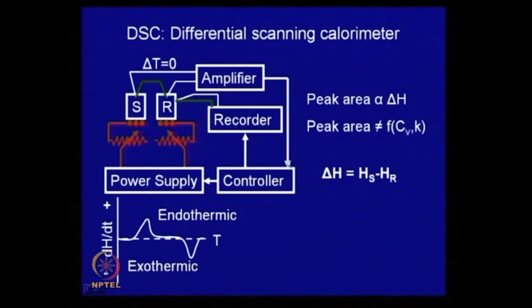And some of these instruments are sometimes also coupled with a load cell. So, you can also monitor the change in weight as well. But let us not bother about it. So, I think what is important, why I spent some time on thermal analysis, is because very often to explain how the microstructure evolves in a material, we will be looking at the cooling curves and how the transformation takes place. You can get a lot of information from DTA and DSC plots.